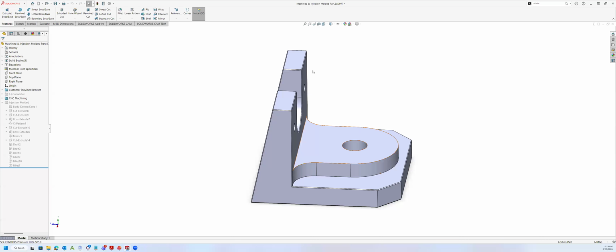Third operation, machine down. You can machine down all of this, and then fourth operation is drilling in your holes as necessary. I could be slightly off on the sequence that I just described, but it helped this new machine part reduce the total amount of operations from probably about 7 to 4, or 2 or 3, sorry.